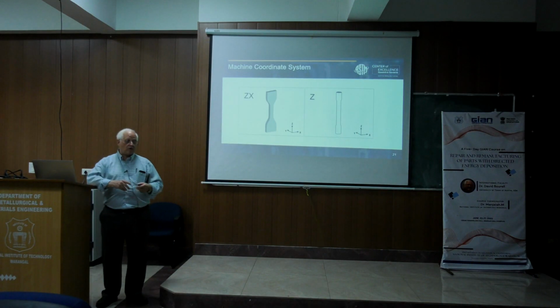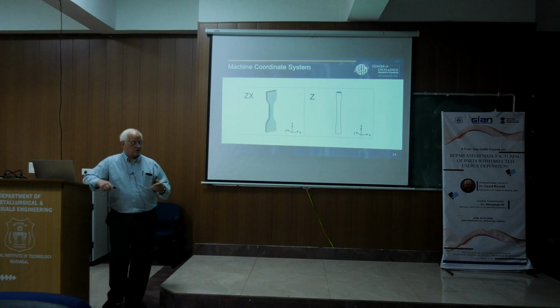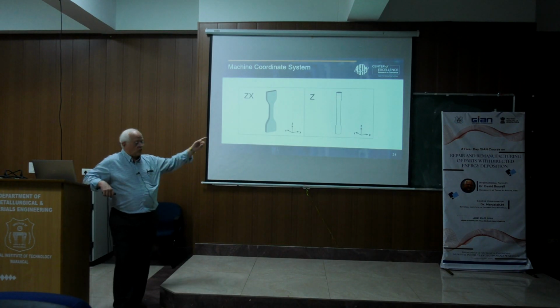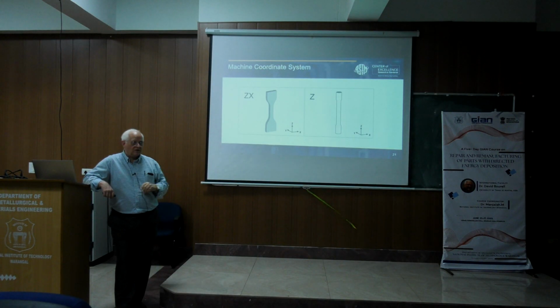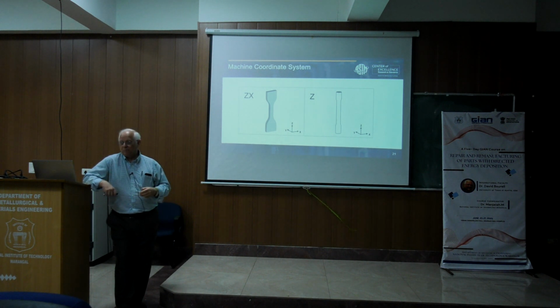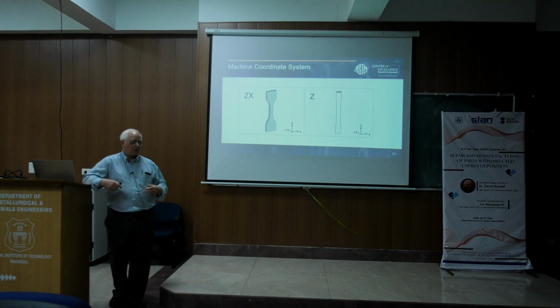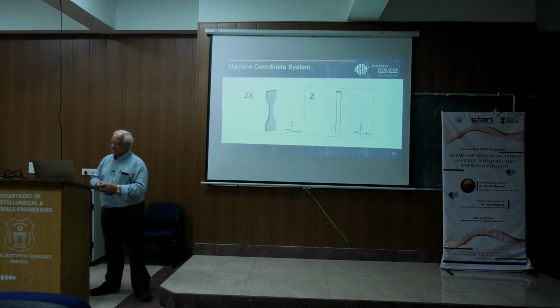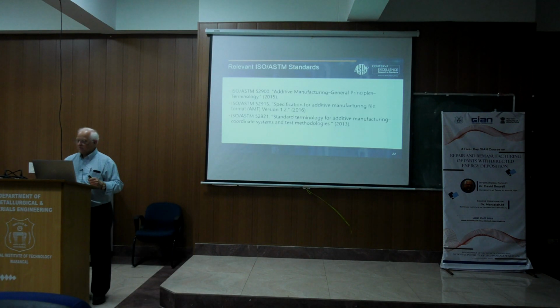And this is extremely common, where we would talk about, for example, maybe you've seen this yourself or used it, say for tension samples, whether it's a dog bone or a cylindrical sample, we talk about that it's a Z sample or an X sample or a Y sample. Z being really popular, right? So we talk about a Z direction build or maybe an in-plane build, which would be say X or Y or something in between.